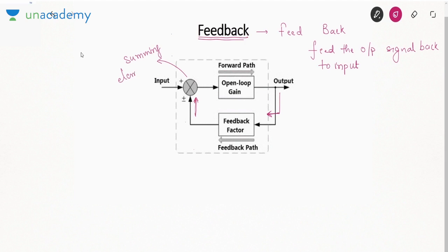This we very well study in control systems. See, we have marked the positive terminal with the input, that is Vin, and suppose this voltage is Vf. It has a plus as well as a minus sign, that is, there are 2 possibilities. This, suppose, is Vd. Vd is Vin plus or minus Vf, or let me call it Ve, because most of the time it is called the error signal.